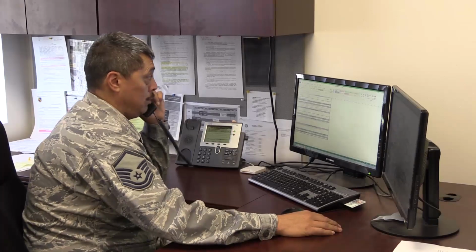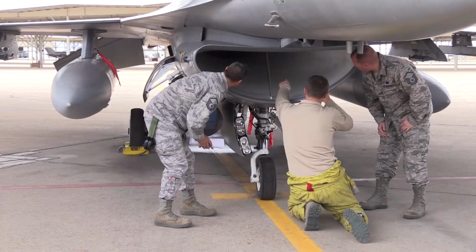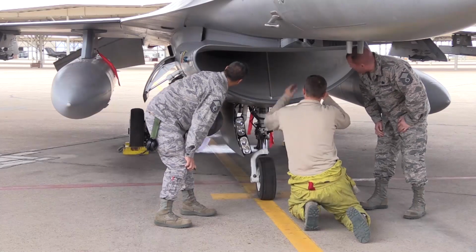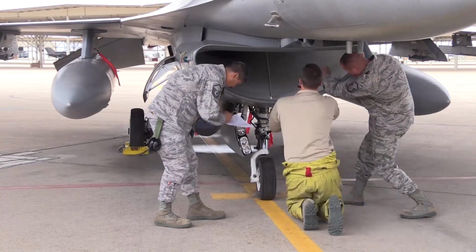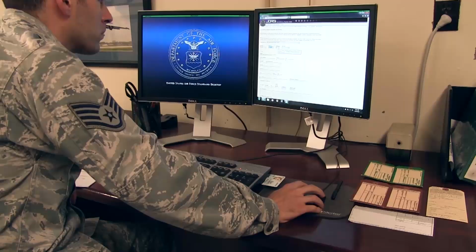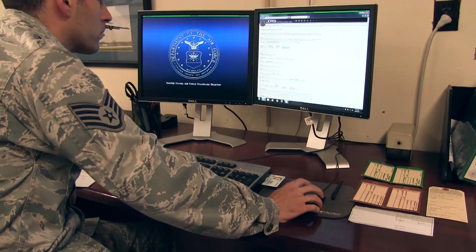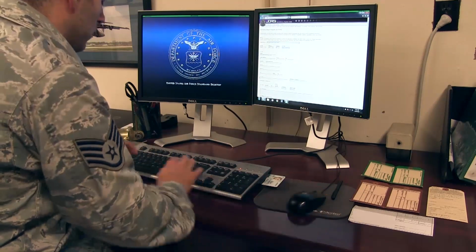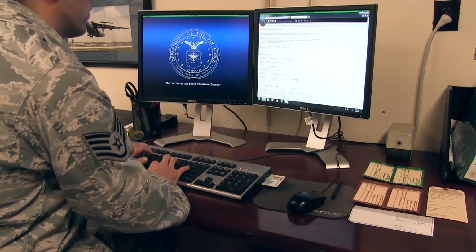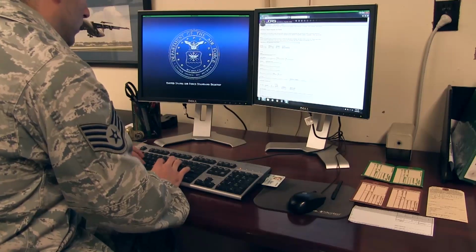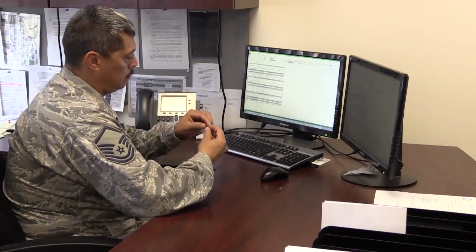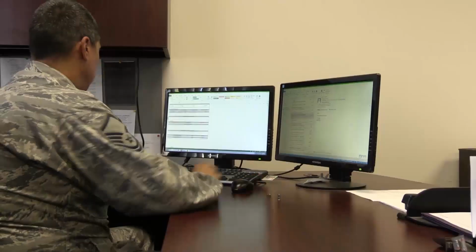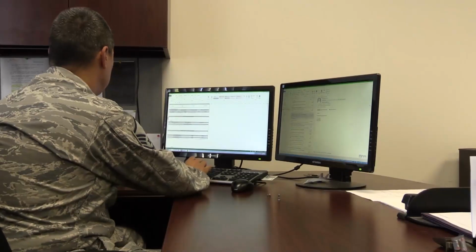Prior to returning engines and modules to the depot for investigation, units must make every attempt to determine the root cause of FOD-related mishaps. An information deficiency report will be completed and forwarded to depots for FOD mishap engines. Ensure the container is properly marked and packaged. The Wing FOD Monitor will provide the initial FOD investigation report and any follow-up reporting required until closeout.